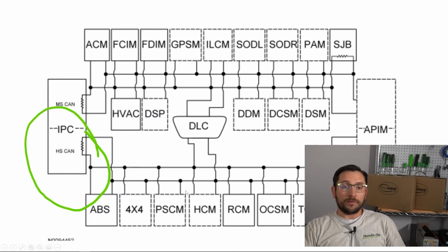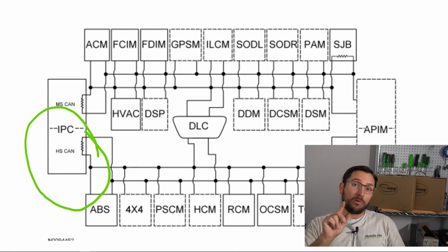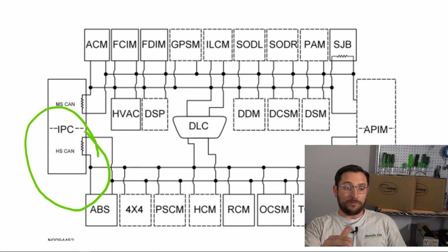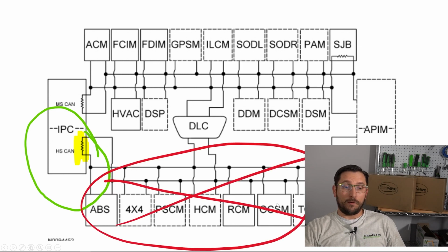Let's take a look. This is a network diagram from Ford, and I'm going to tell you right now, you have to be really careful on the types of diagrams you get and where you get them from. Guys, I believe this is from AllData. If you look under description and operation of the CAN bus, you'll find a picture like this, and it's showing that we have some terminating resistors here in our cluster and also in our powertrain control module. But here's the thing, I want you to understand that the rest of this network may or may not make sense the way this is laid out. This diagram is not an actual real diagram of how the system is laid out. This is more or less maybe what we call a block diagram or just a general overview. So don't ever get hung up on looking at a diagram like this.